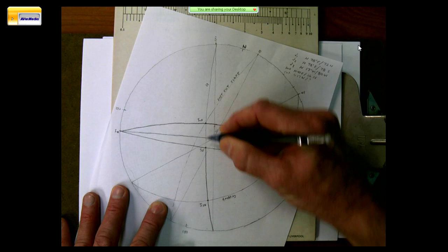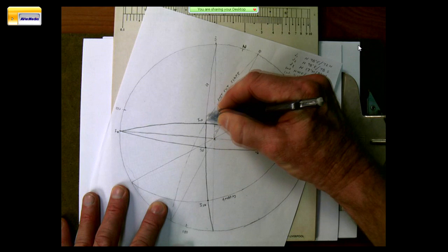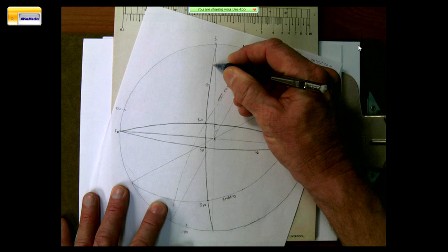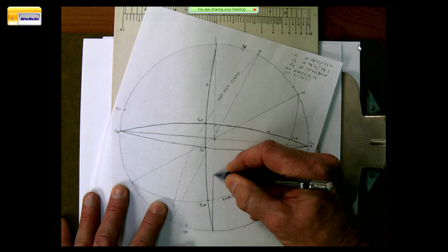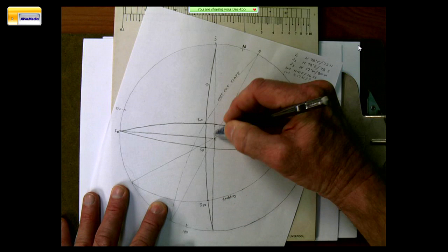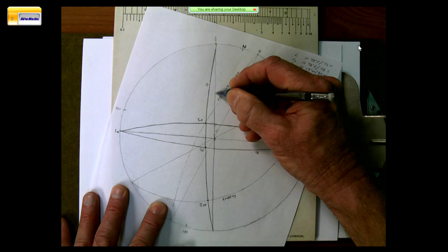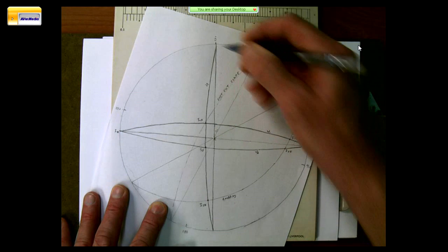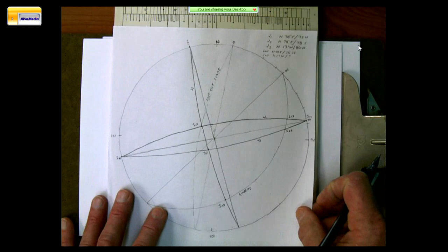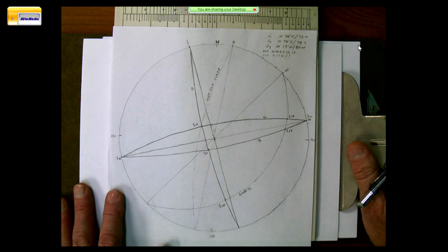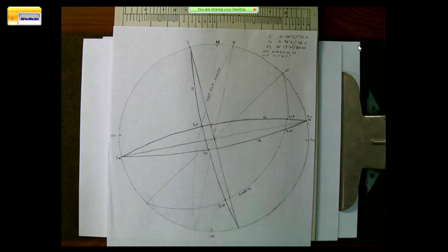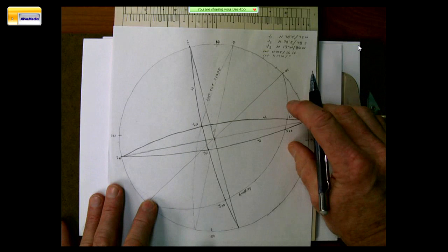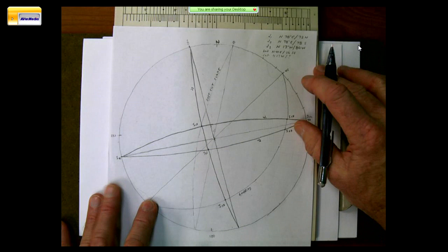And so now I have another, and this is the orthogonal set. This is the one that's almost 90 degrees to the other one. And so that's what you'd expect to see. And now I have 3 sets of discontinuities plotted. Now I rotate back to N, and I look at this, and I say, okay, does that make sense with what I'm seeing out there? Typically, you'll have two sets that are mutually orthogonal to the bedding, and then another set that's maybe not as pervasive if you have bedded sedimentary sequences.